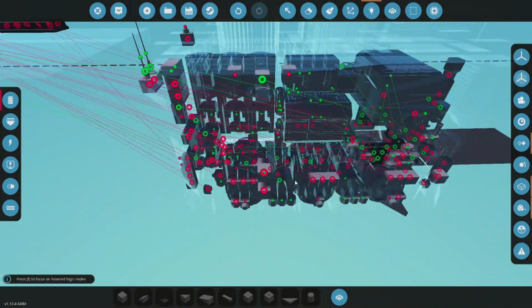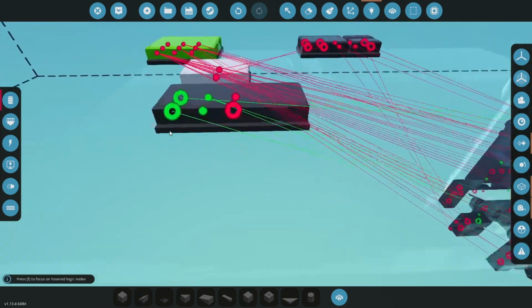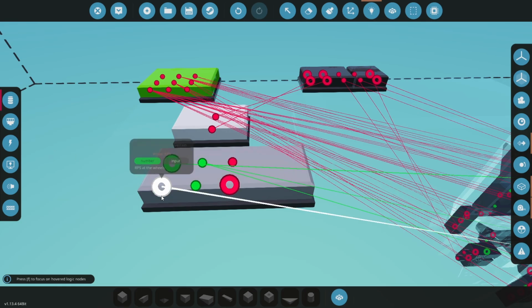That matters because if your locomotive is moving 100 kilometers, but the wheels are spinning at 90 kilometers, then you probably have wheel slip. You might not have wheel slip in that situation. If your locomotive is moving at 50 kilometers and your wheels are spinning at 100 kilometers, then you'll have wheel slip. So that lets the system know it needs to slow down, adjust the brakes, etc. It needs to figure itself out.